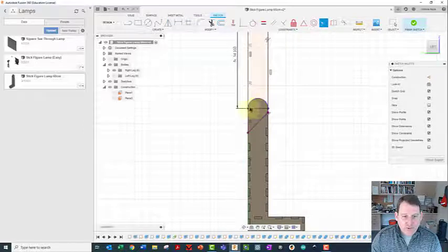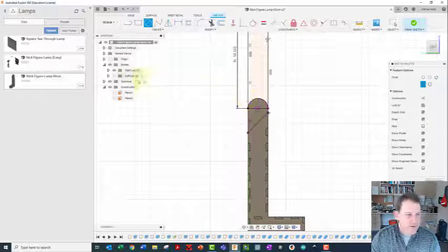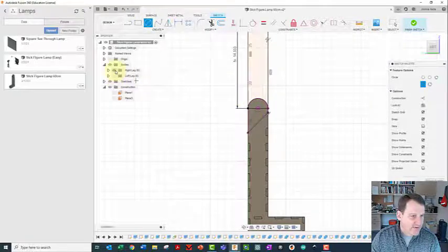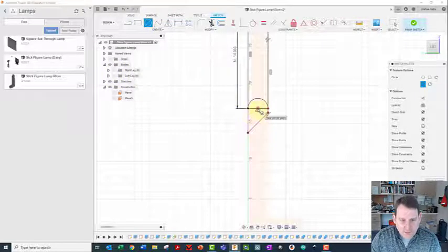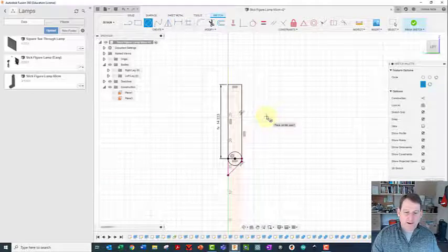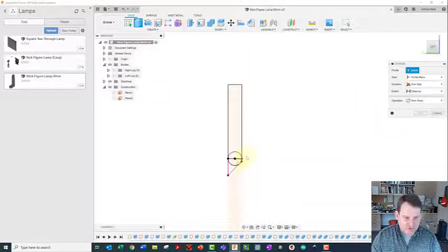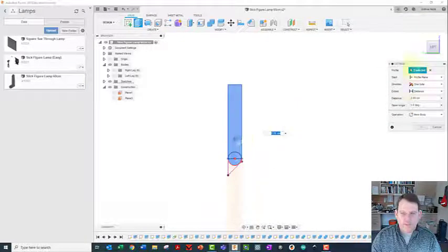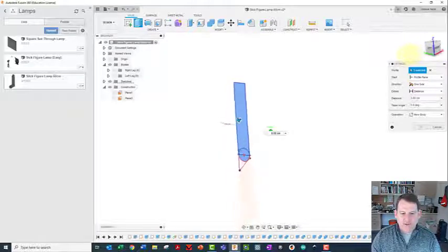Now I just need to do the rounded over part down here. So I'm just going to grab a circle tool. I'm actually going to hide the leg now that I know where everything is. I'm going to draw it out there, and I'm going to get that circle. And right there is my first outside thigh. So I'm going to extrude. I want this piece, and that piece. And I want to make sure I'm extruding back in.